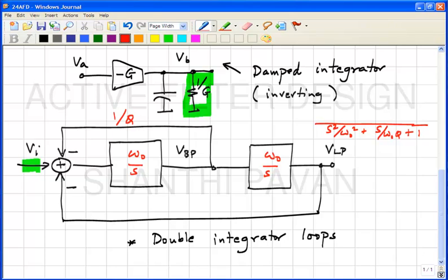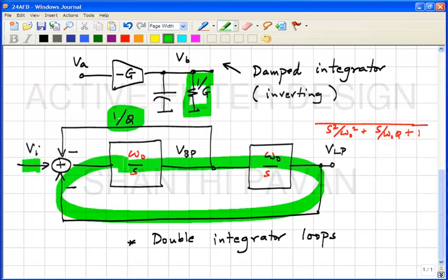And why does that make intuitive sense? Can you stare at this diagram and tell me? No. This is fixed. Please note that this is fixed. When you have non-idealities in the integrator, what do you think happens? This 1 by S is going to become 1 by S times 1 plus S by omega p. Correct? So you can understand in many ways, at a very crude level, you can say that there is increased delay, there is this feedback loop here, and there is increased delay.